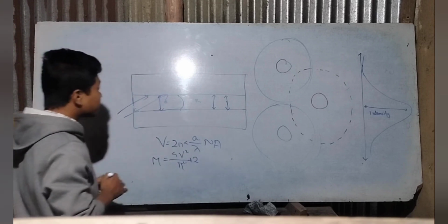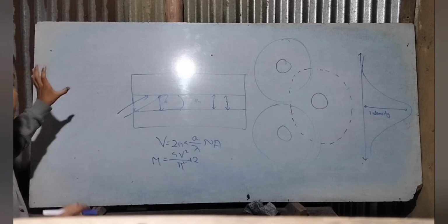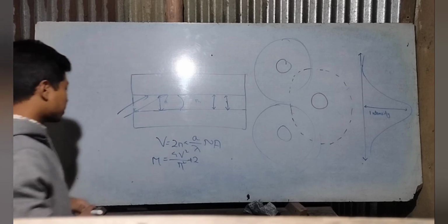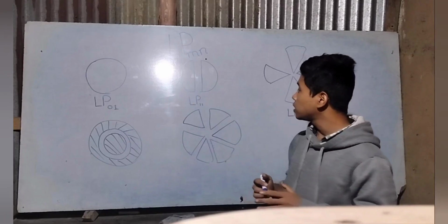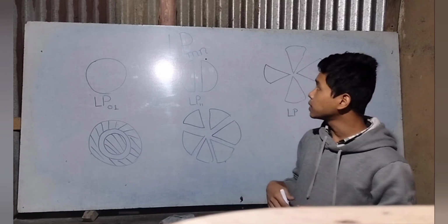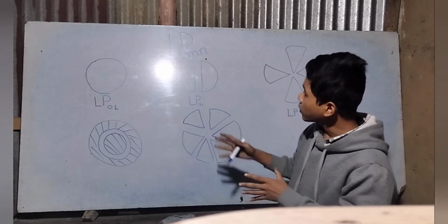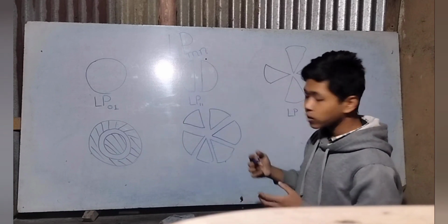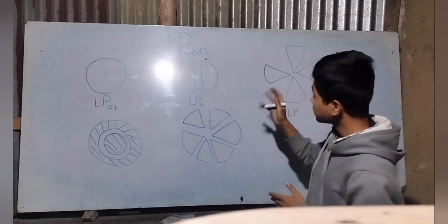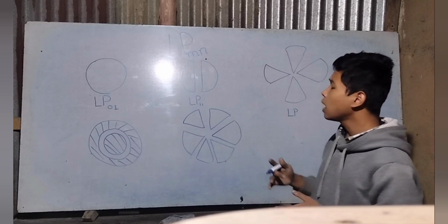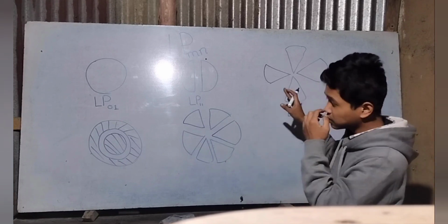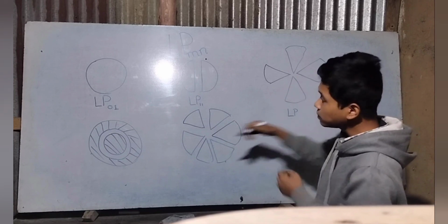So next we'll be looking at the number of modes and the speckle pattern. For the last topic, we will be focusing on the modes and how we name them. All the modes follow a particular naming pattern, that is LP MN. M usually represents the radial, while N represents the azimuthal. But for our own basic understanding, we'll be using some simple way of naming them.